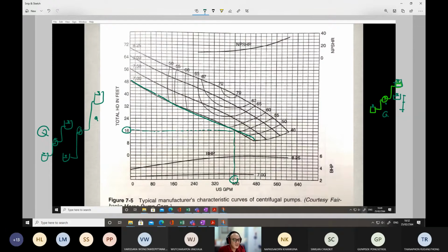So this is how the centrifugal pumps work. We are talking about the pumping capacities. We are not talking about the systems, okay? This is the capacity of the pumps. So they can actually carry the flow rates, but at some certain head. So if you want to pump with a larger head, then you only get a small flow rate, okay?